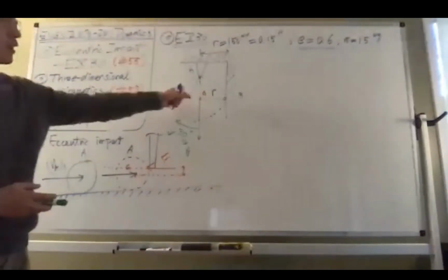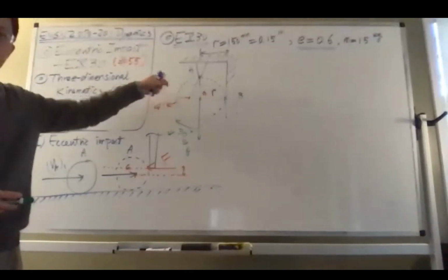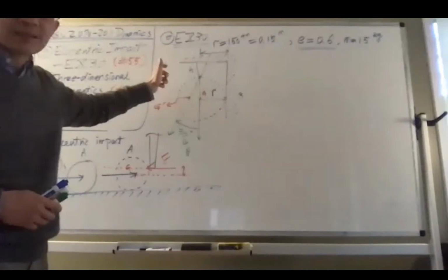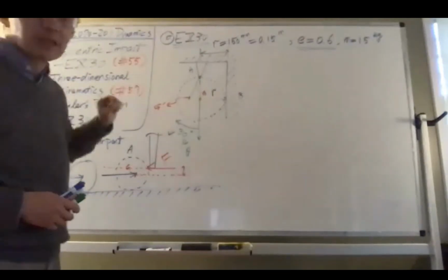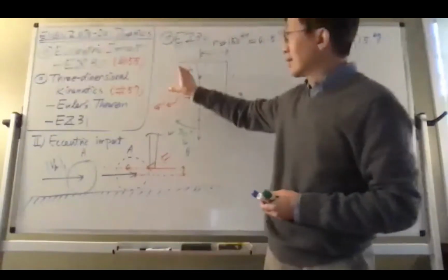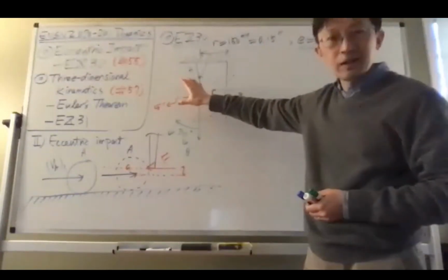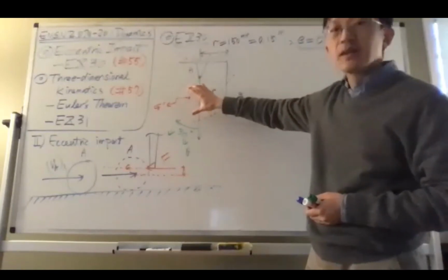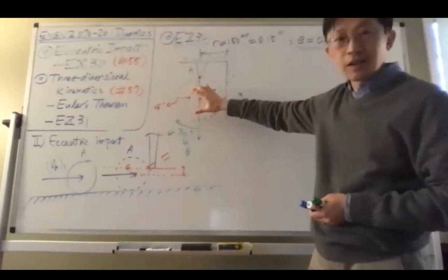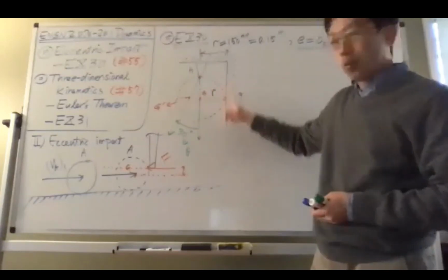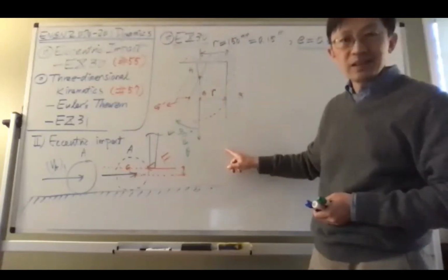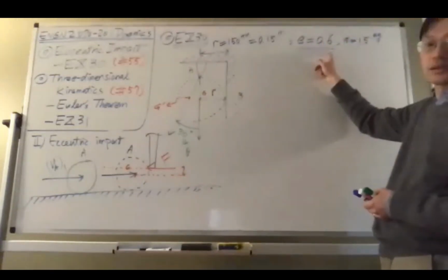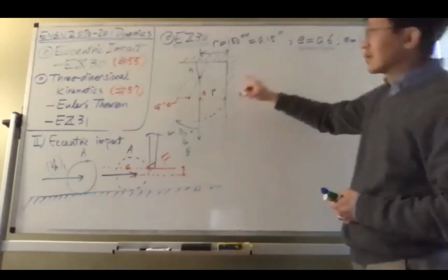We want to know that after lifting the disk by 30 degrees, and of course there's gravity, we're going to release it. And once releasing it, what happens to the disk? The disk is going to spin, right? Because of gravity, it's going to swing back to its original position, but this time it's going to carry an angular velocity, which means that it's going to run into the wall. Correct? Once it hits the wall, impact occurs, which means there's going to be a rebound.